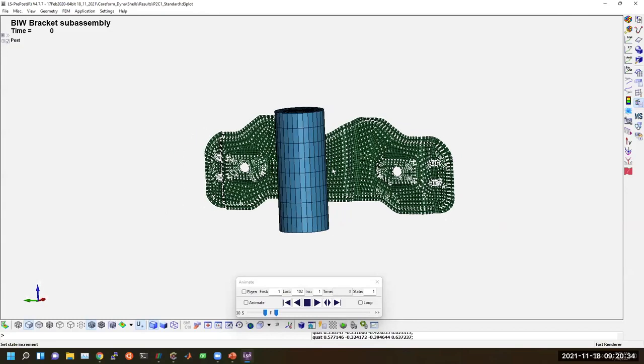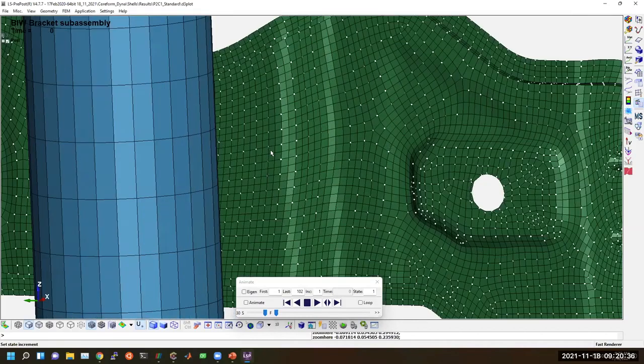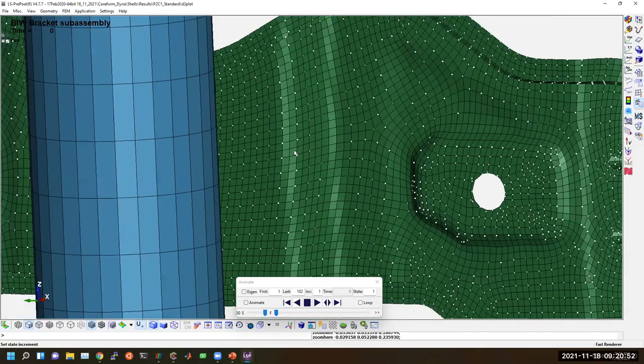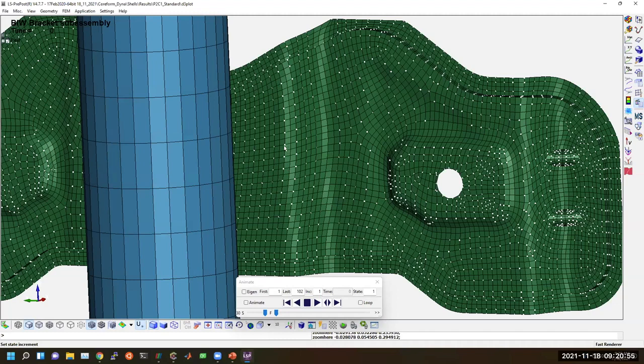One of the things to note, which has been asked a couple of times: right now, LS-PrePost visualizes the interpolation facets for this higher order basis. So actually, you're seeing about twice the density of what's actually going on in ANSYS LS-DYNA. The white dots are actually the control points of the U-spline, which can be thought of as the corollary of nodes in traditional finite elements. So each control point corresponds to a single basis function.